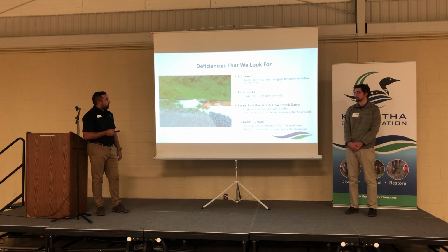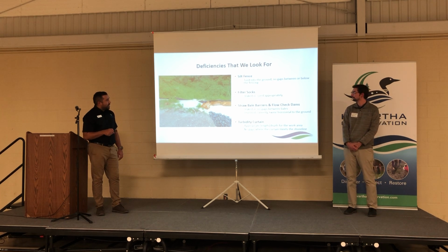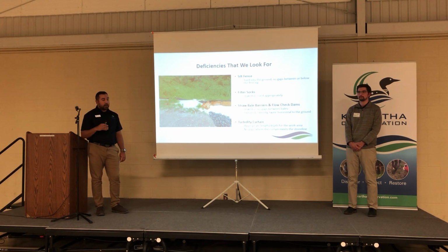So these are some of the deficiencies we look for. I'm sure you can see quite a few in there. With the silt fence, we'll look to make sure that it's toed into the ground, there are no gaps between or below the fencing, and that it's not overburdened with silt. Generally, we like to tell folks to clear out any silt accumulation when it reaches about a quarter or less up the silt fence.